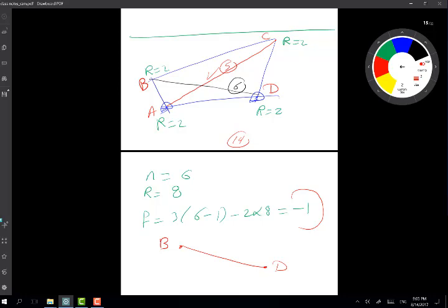So now link number 6 has to be highly machined and highly accurate, and you pay more money to manufacture this specific link. This is signified by the -1 number that we got. The mobility, which is -1 here, suggests to me that when I'm manufacturing link number 6, I'm going to pay more money.